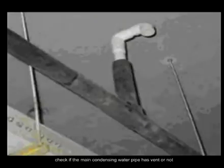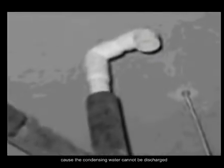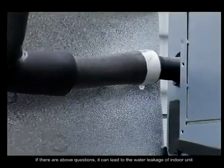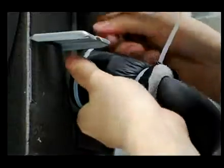Check if the main condensing water pipe has a vent or not. If the main discharge water pipe is jammed, the condensing water cannot be discharged. If there are any of the above problems, it can lead to water leakage of the indoor unit. Please modify it according to the requirements of the technical manual.